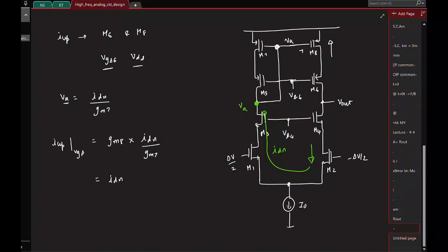Okay, so this takes care of the contribution due to gate to source. Now only drain to source is remaining. Since we have taken the contribution from gate to source, we can basically assume that for now it's not there, only this is there. And now looking up, you see only this cascode here, and we know the impedance. Okay, is that fine?